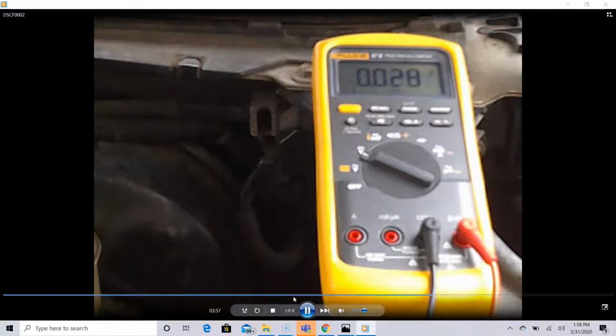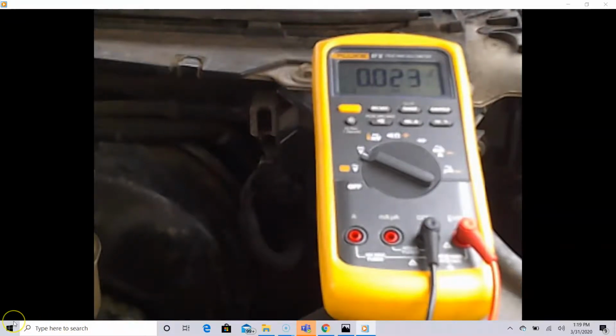Okay, we see right now we have, but you guys saw the voltage when I first cranked it. That's the number that would be the important one. Right now, this is still an acceptable range. We don't want to see too much difference between the two sides. Right? So, again, we rev it up. We look for a change. If it's not a change and it's low like that, then we are adequate. Okay, so that was checking the integrity of voltage drop on the power side and the ground side.